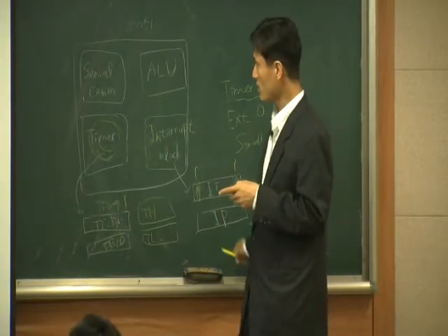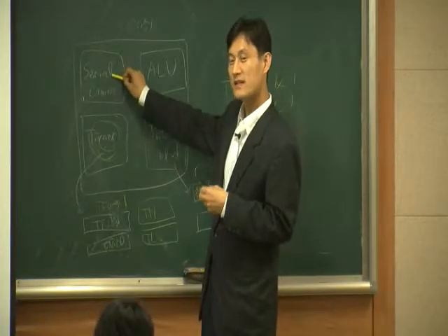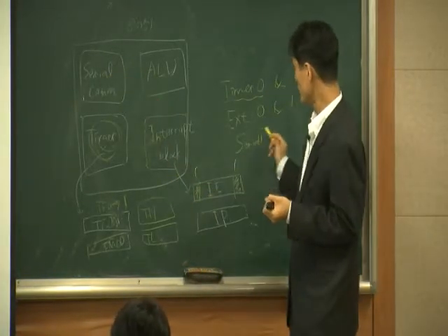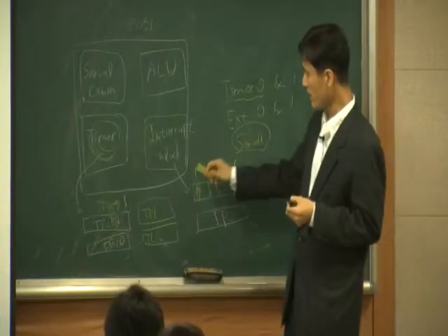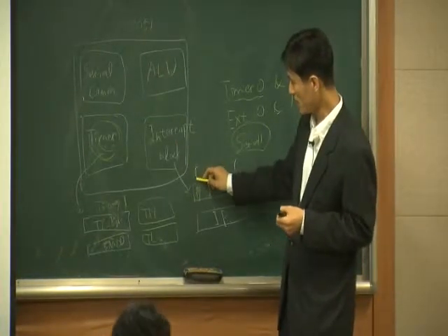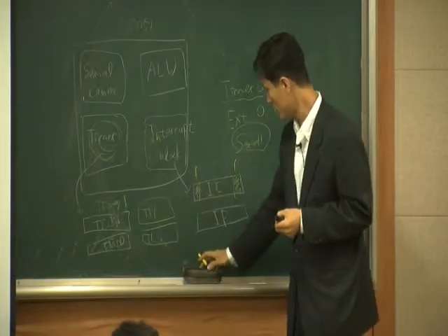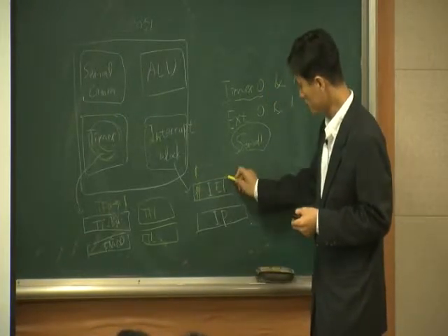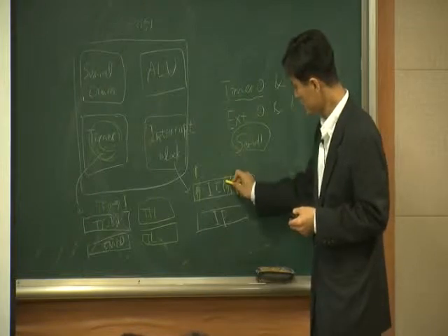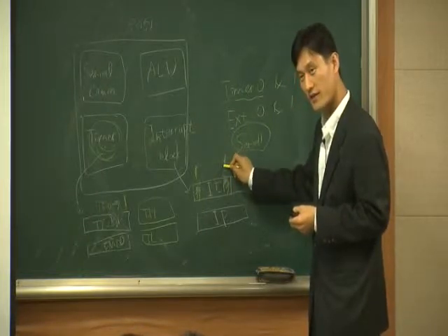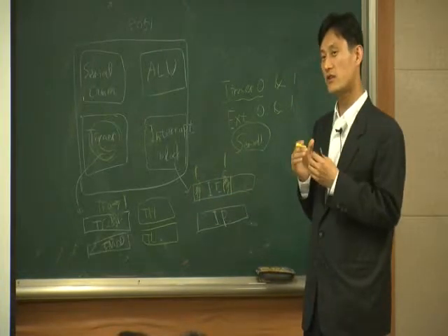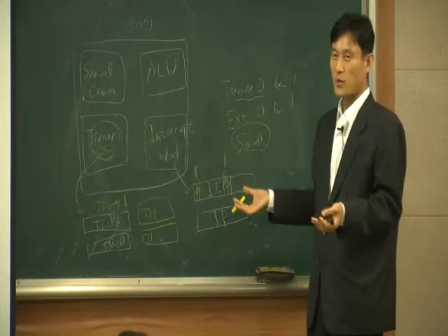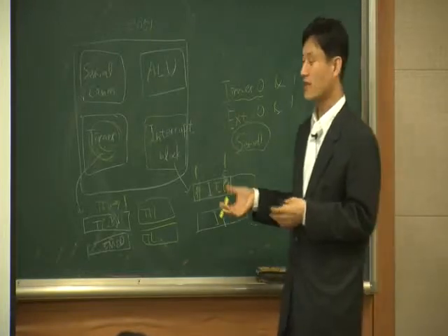And today what we're going to talk about is this one. It's the same thing. If you want to use the serial port interrupt, in that case, again, you have to program the global interrupt enable to 1. And also, you have to set the serial port interrupt to 1. Okay? Once you do that, now you are ready to get a serial interrupt. But you are only ready. Nothing happens.